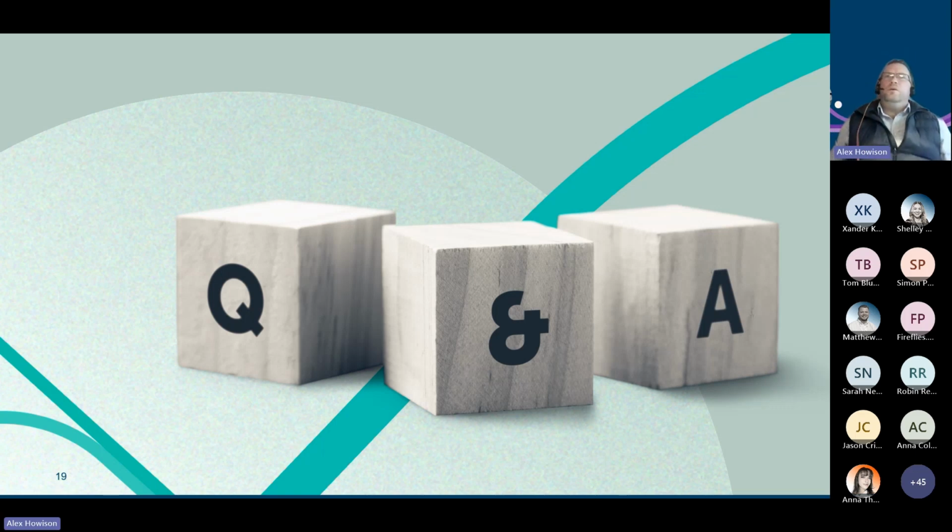Well, I think I'm quite comfortable in the fact that we've already got an example of where a DNO is allowing more than that, and I think ultimately it is about having that engagement there. I know the 1.25 is a traditional approach engineering requirement, but the use of G100 and putting in an optimization system that gives a suitable level of confidence that we can manage the loads and generation behind the meter.